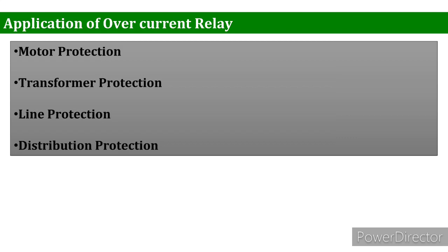In distribution protection, overcurrent relaying is very well suited to the distribution system protection for the following reasons. It is basically simple and inexpensive, and along with that, the operation is very simple.